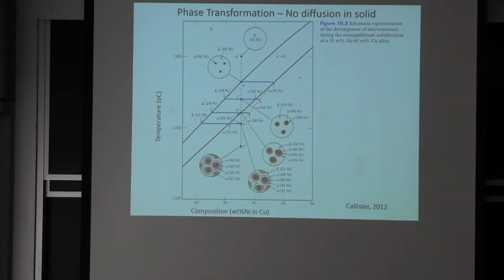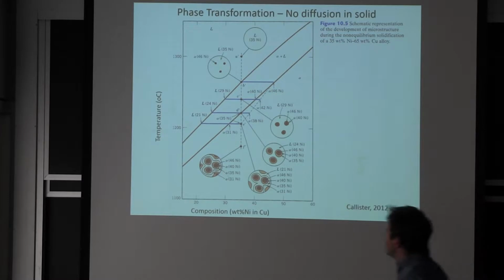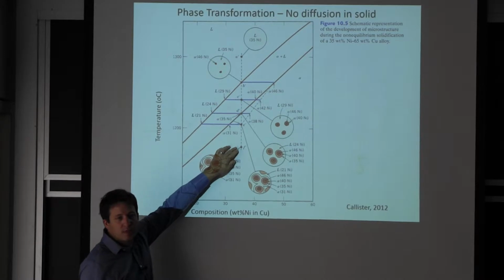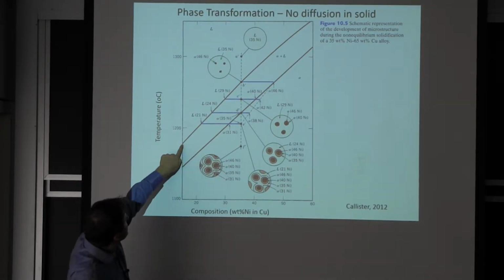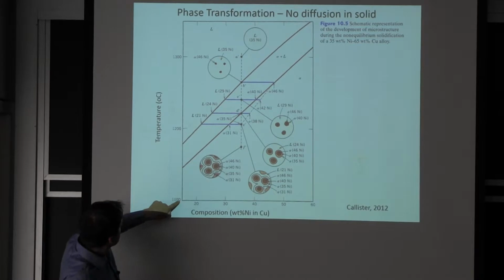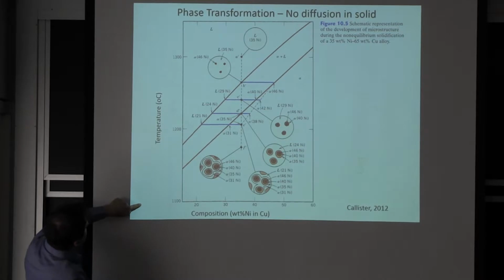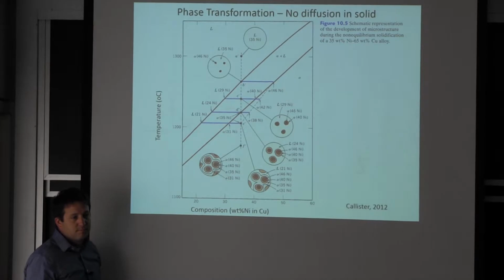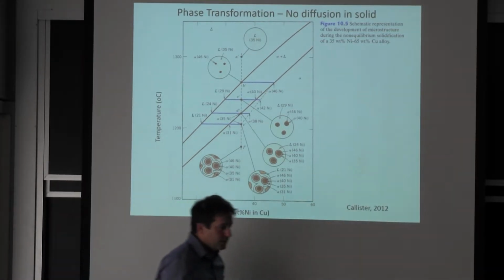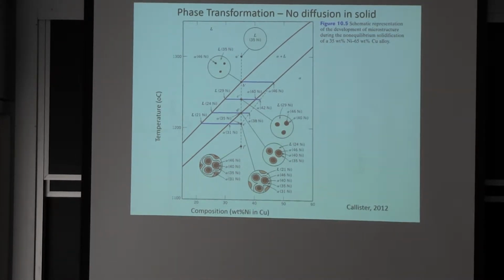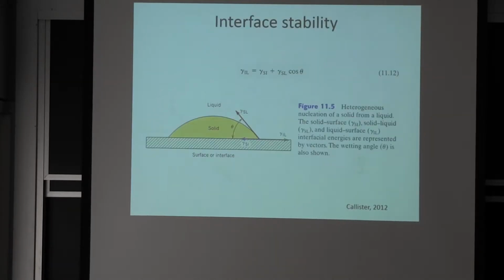And over here, we still have our schematics at 1175 or so. We still have a liquid, because it's the last bit of it. This doesn't go to 0, so if I take it to 0, I could have a liquid potentially all the way to 1100 in this particular situation where we're cooling really fast. So it's something you need to keep in mind when we're going to be talking about aluminum alloys.